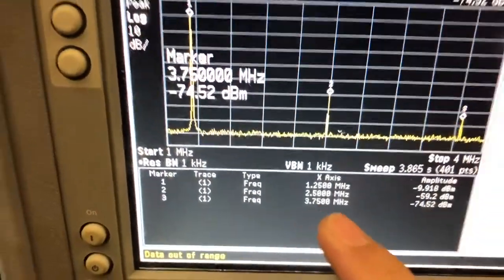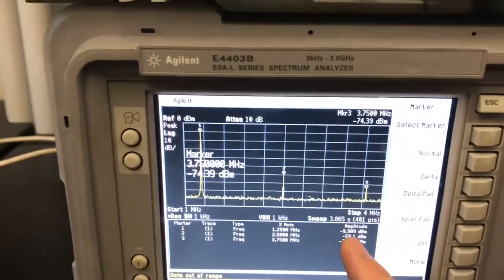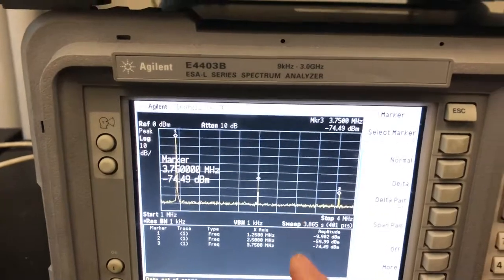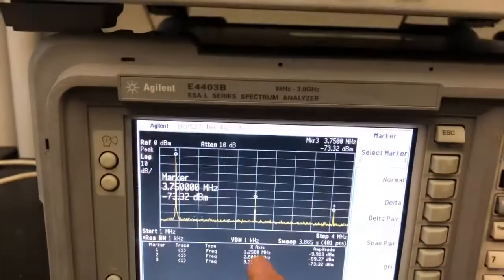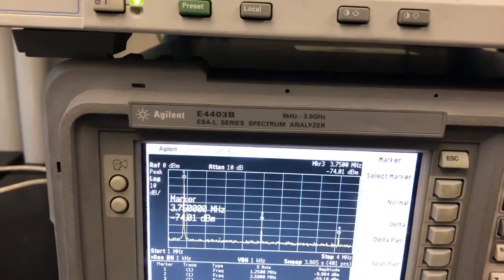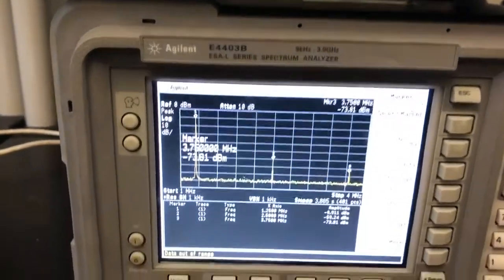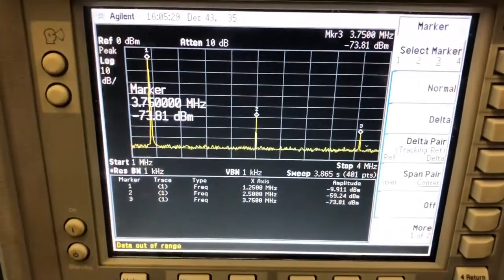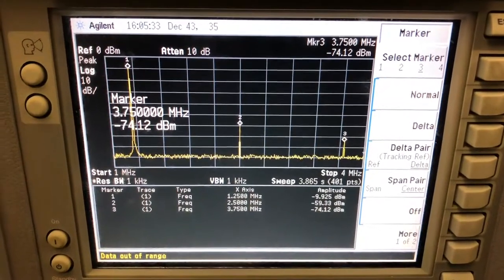these are the amplitudes. So when we have a circuit or an active circuit, it will have harmonics. This is a very good signal generator, with higher harmonics very low in comparison with the fundamental. It's almost minus 50 dB down for the second and the third. So this is the last part. We take a photo, screenshot, and that's it. Okay, so this is the last step you work on.